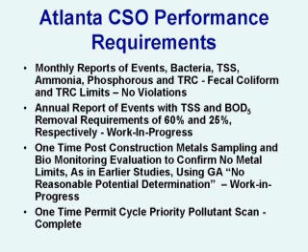The performance requirements for the City of Atlanta CSOs is to provide monthly reports of CSO events where they sample influent and effluent, and they report the bacteria levels. In Georgia, it's fecal coliform bacteria, TSS, ammonia, and phosphorus, and they have a TRC, total residual chlorine, level they have to measure, and there's a limit for fecal coliform and total residual chlorine. So far at the facility on the east side that has been operating for 1 year, there are no violations